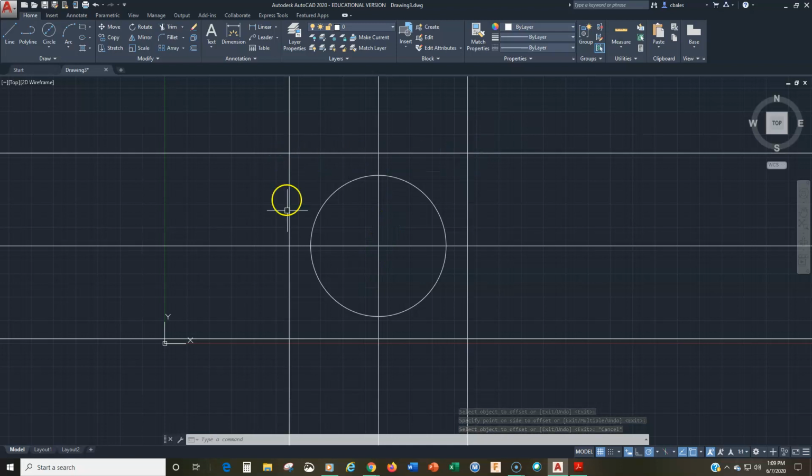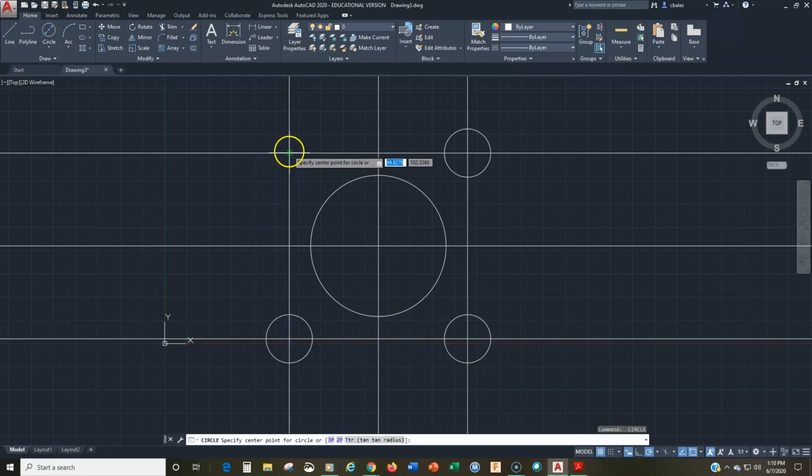Let's put the circles here. Those are diameter 26. So we'll go to Center Diameter and 26, right? And remember this: hit the space bar to bring back the last command, which is circle. Pick the intersection right here, and then hit the space bar to pick the last radius or diameter. Okay, space bar, pick, space bar, space bar, pick, space bar. All right, so we have our 5 circles laid out pretty quickly. Aside from my goof ups, everything is going well.